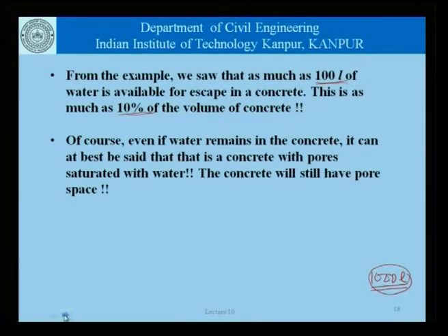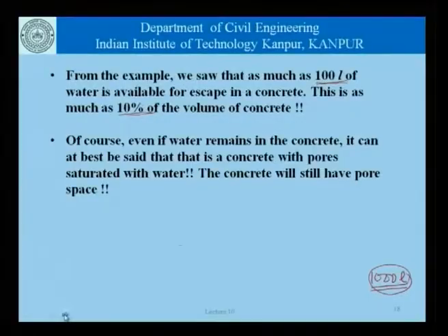Even if the water remains in the concrete, it can at best be said that that concrete is one which has pores saturated with water. The concrete still has pore space. So, the fact that water is present in those pore spaces does not take away from the fact that pore spaces have been formed. That space is not solid hydration products.